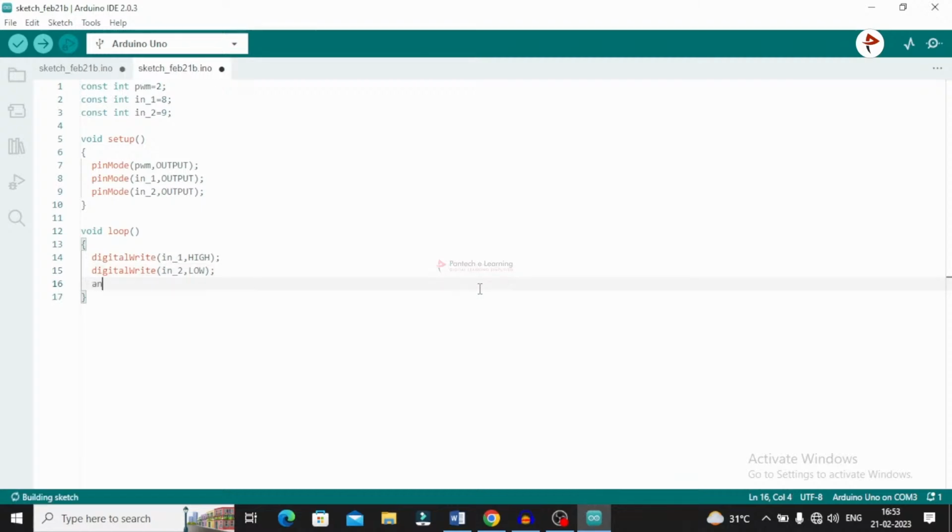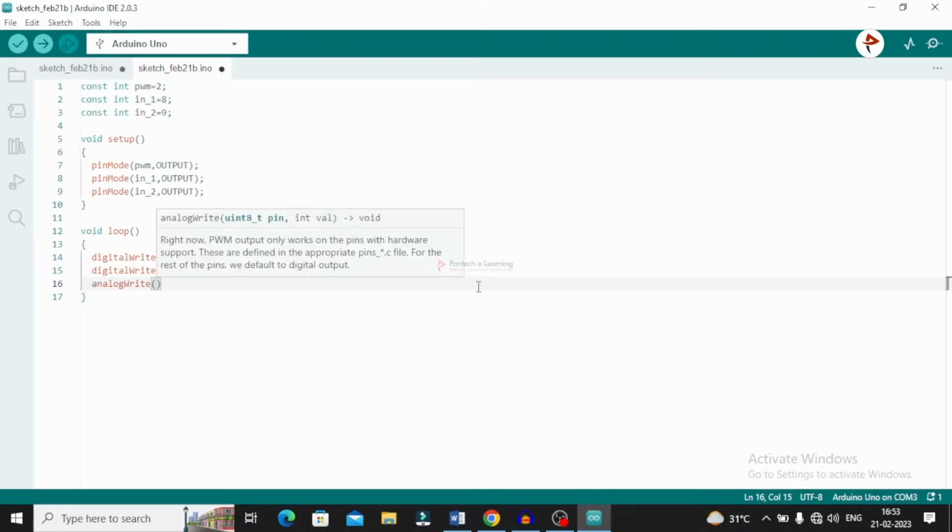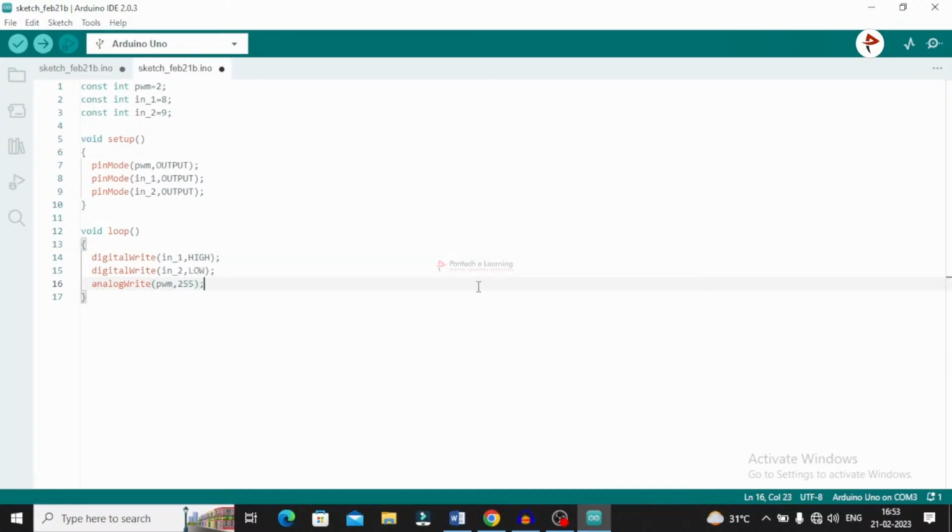Then let's just mention pulse width modulation. So inside pulse width modulation, let's give the maximum value 255. Speed, I'm mentioning speed here. So setting pulse width modulation of the motor to 255, we can change the speed of rotation by changing the pulse width modulation input. But we are only using Arduino, so we are using the highest value to drive the motor. Then I'm going to give a delay of like 3 seconds, and now I'm going to brake my motor.